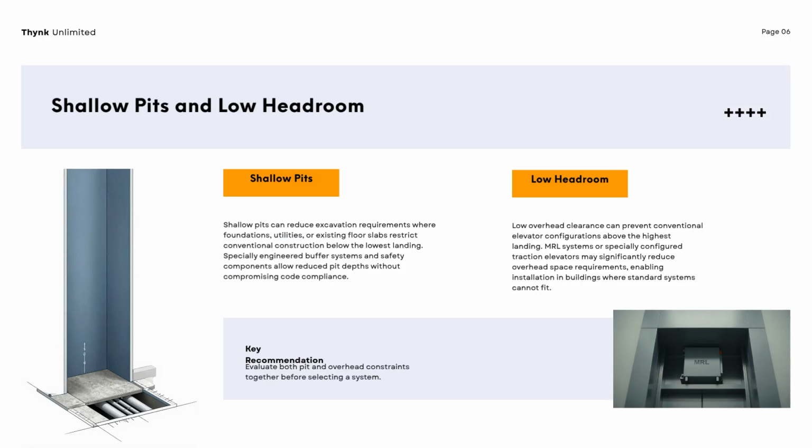4. Which elevator type is suitable? There is no single elevator system that works for every existing building. A machine room-less or MRL elevator can be a good option when there is no space for a traditional machine room. It is commonly considered for apartment buildings, offices, hotels, and other modernization projects. A traction elevator can provide smooth operation and good energy efficiency. It may be suitable for multi-floor buildings or projects with higher passenger demand.